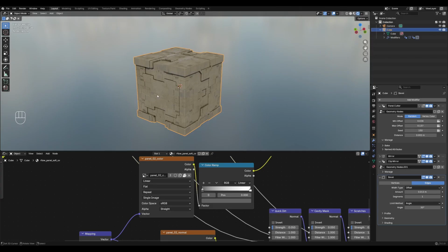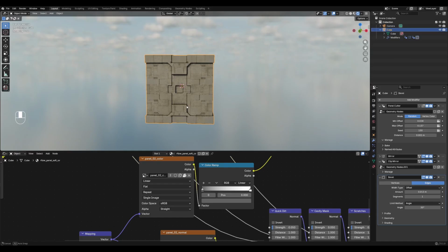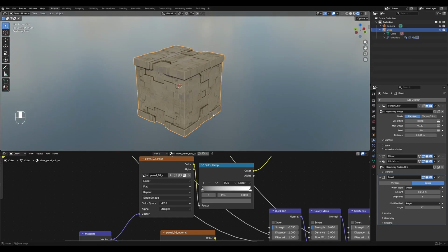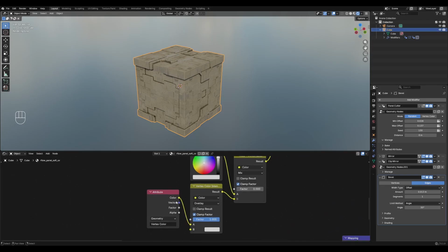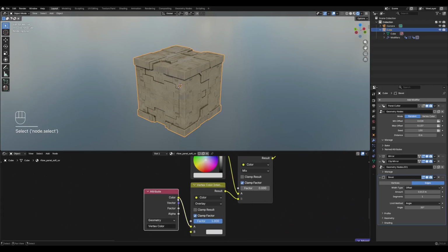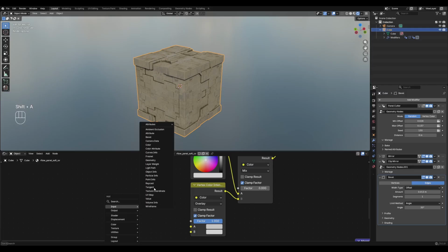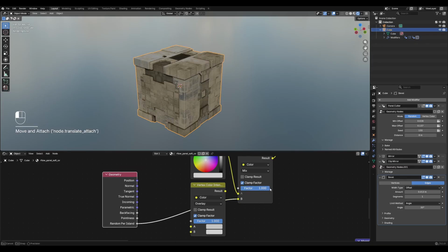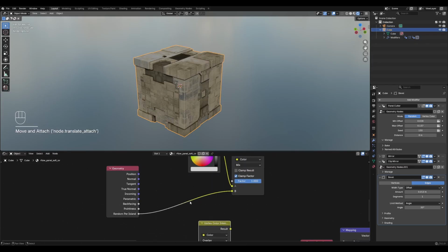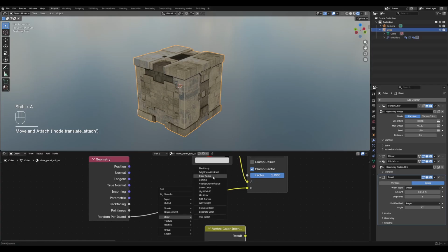You're going to actually generate a different shade value for the islands. We can set the merge distance to 0. And instead of using vertex color, we're going to use, in the input, select geometry, and then random per island, like that, and control this with a color ramp.